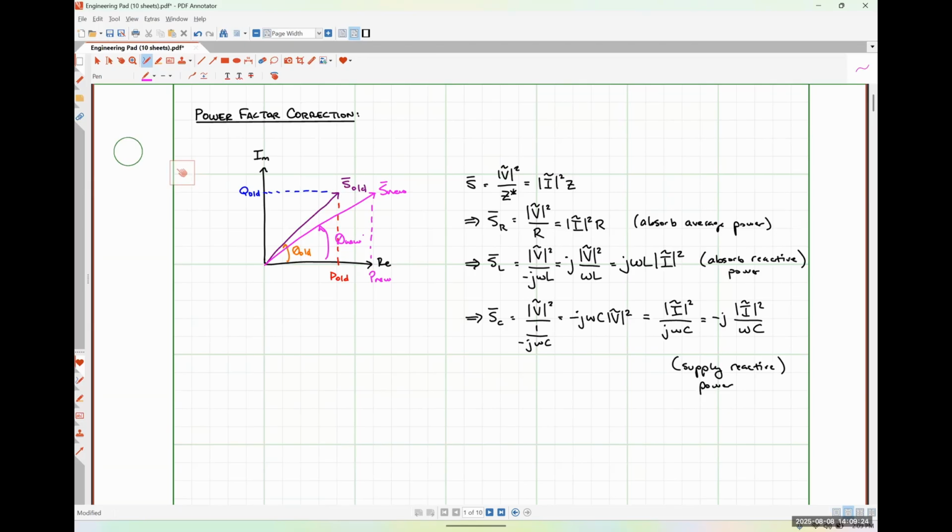So now let me explain to you why this is so dumb, okay? I mentioned it to you on Wednesday, but average power is the power that we as consumers pay for, okay? So essentially, if you try to improve the power factor at which your load operates by increasing the average power drawn, you would be running up your utility bill in order to avoid paying a fine.